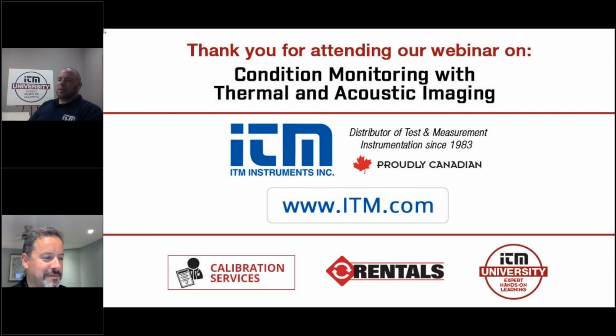So going back to the acoustic camera, the SI-124, how many microphones does it have? 124. So the camera has 124 microphones. It measures frequencies from 2 kilohertz up to 35 kilohertz. More microphones means it's easier to localize from far away, right? Because you have a much broader range of capturing without going overboard. It's a camera to carry and hold.